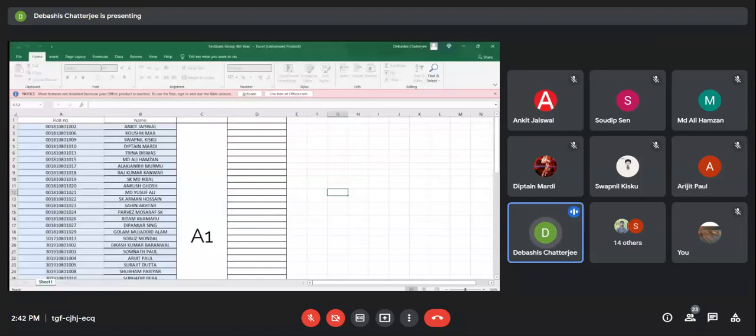And then the kilowatt rating is say 750 watt, and rated RPM is 735 RPM. So 3-phase, 110 volt, 50 hertz, 750 watt, 735 RPM. Efficiency you can assume, but power factor, you can get a tentative power factor of say 0.8. 0.8 tentative. It may not be.